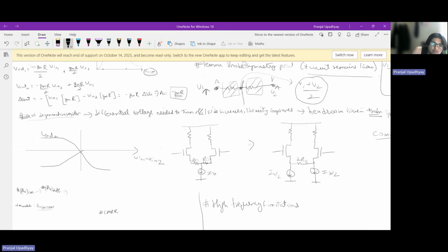the large signal behavior basically appears something like this, and we know that the amplifier is working as an amplifier in this regime only, right? Because here the outputs are saturating and here they are increasing linearly, which implies that only in this regime it is working as an amplifier. So if I want to increase this range of inputs for which it can function as an amplifier, I am using degeneration, and that's the basic idea over here also.